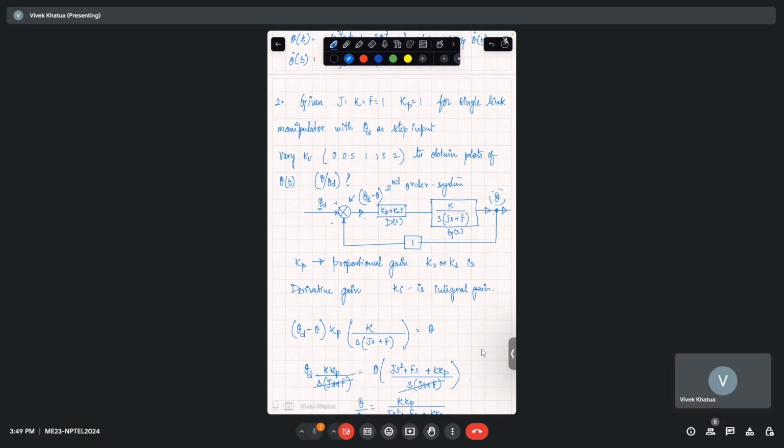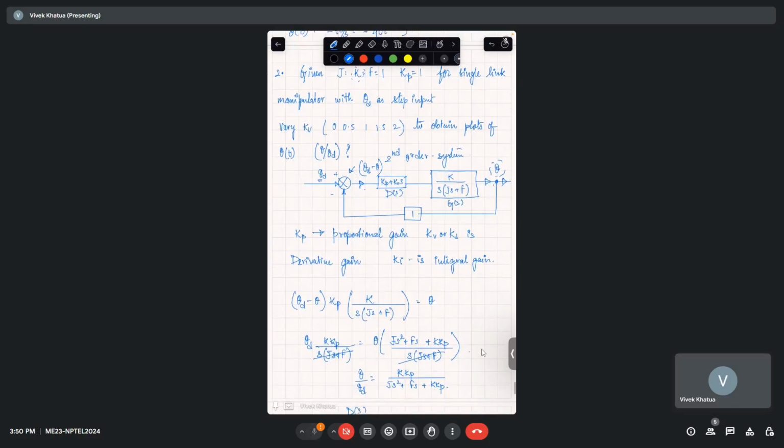It's the build of your motor that is encapsulated as K: how much winding has gone in, the number of turns, the build of it, that is your structural response of it. All of it is combined in K. So the K term is basically your motor's or your link's build.